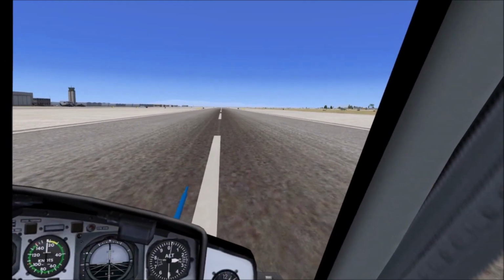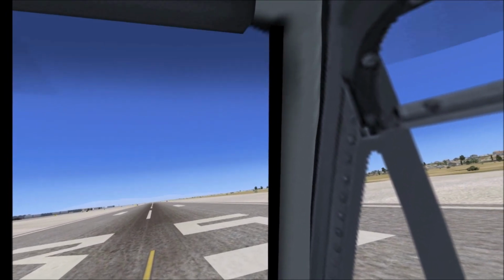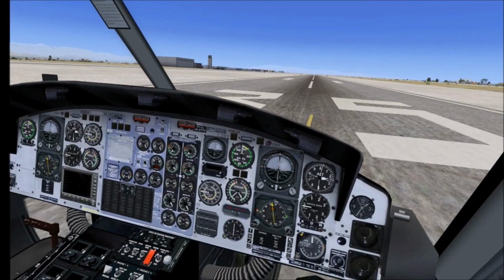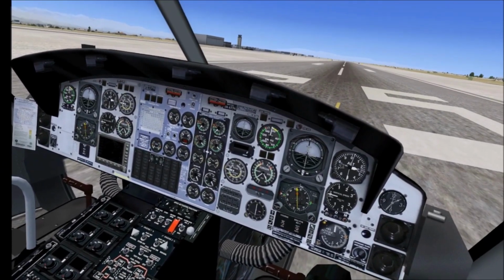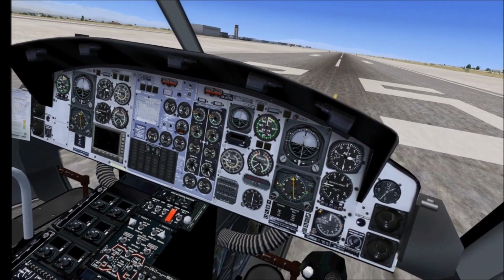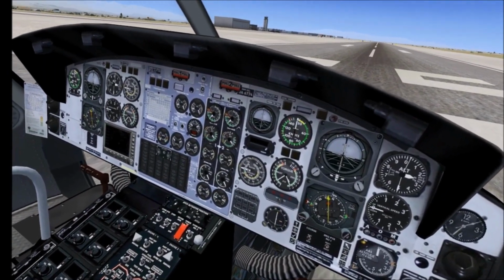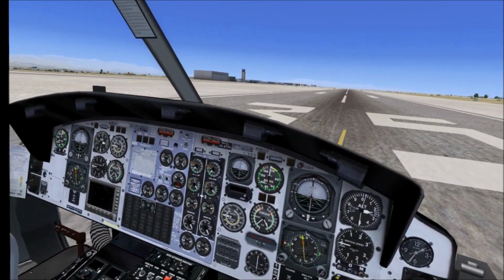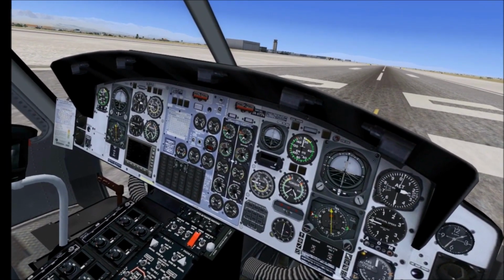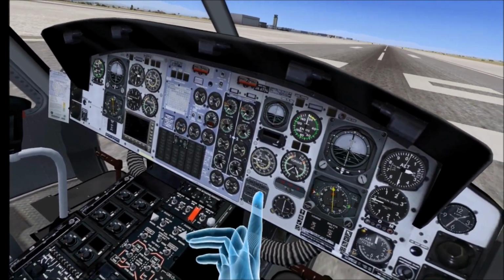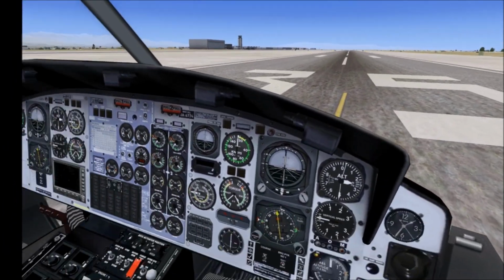Okay, moving on. All right, next thing we're going to look at is our rate of climb performance. What we've done is we brought the aircraft back to 9,000 pounds. We're using the same parameters that we used for the X-Trident Bell 412 that we did in X-Plane in the last video. So we're back at Henderson Airfield. All those conditions are the same. Same density altitude, pressure altitude. Temperature, still 20 degrees outside. We've got a 9,000 pound aircraft here, sitting on the approach end to 3.5 left.